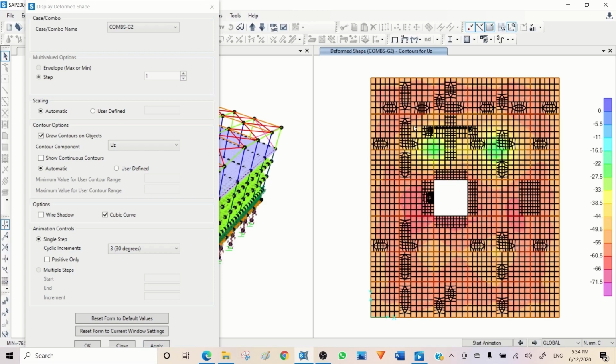Personally, what I do, I remove all levels below and I just keep this level and levels above plus the columns below this level of the slab, and then put rigid support at that column level and then run the model again, and that's a good indication for me to eliminate all displacement due to other interactions from lower levels, and then I can see the displacement for this level of the slab and justify if it's okay or not.